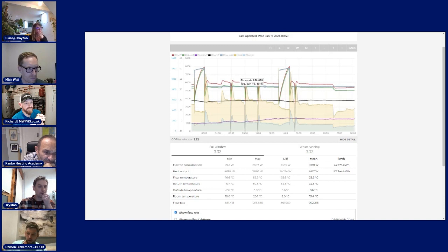So with the IMI tool, we just thought we'd change them out, and like I said, we saw that improvement just grow. It made me start thinking about what valves are right, because we size these valves properly as well. On the first one I did, I went everything by the book: high flow valves over 150 litres per hour, normal valves under that. And you know what? I haven't really got the answer to that question, because it's pickled my brain loads and I can't answer it. But it just works. It works better. I thought it'd be perfect.